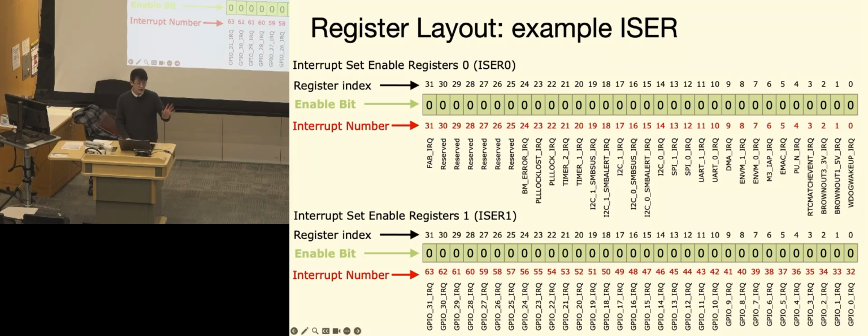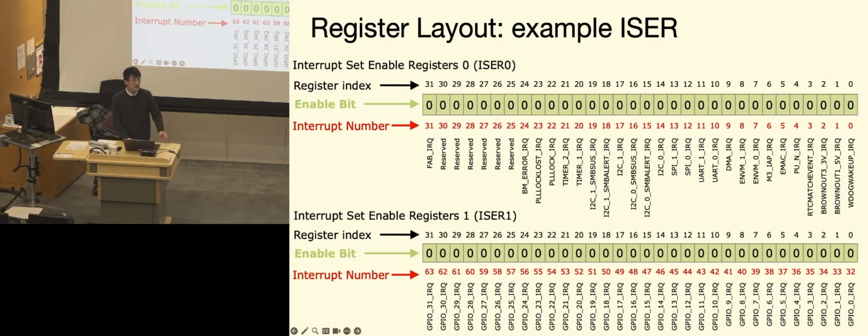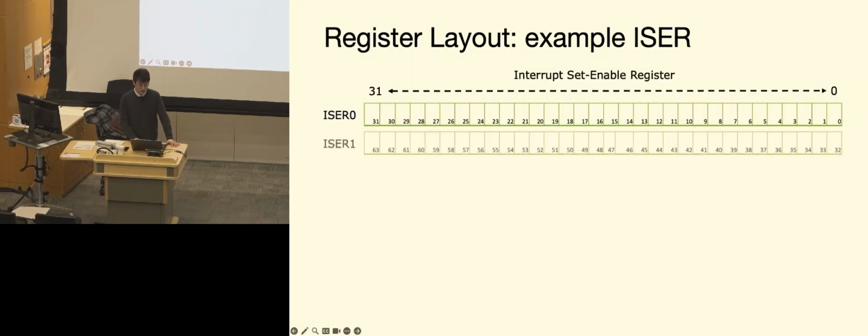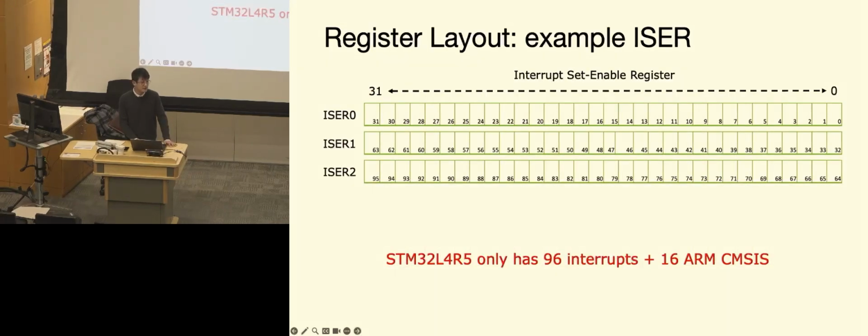And I think the way they map it is pretty similar to the peripheral addresses that we talked about before. Like within a peripheral, how do we know which registers are enabled or not enabled? You can think of them as a similar control mechanism. We will have multiple of these 32-bit ISERs to accommodate enough interrupts. For the ones we work with, which is 96, we actually have 3 of those ISERs, the enable registers, to have enough enable bits to map onto each of the interrupts.